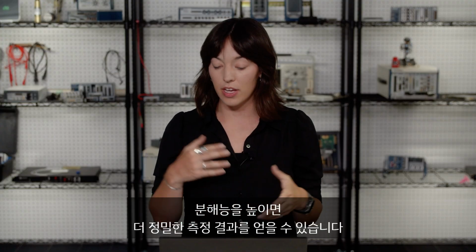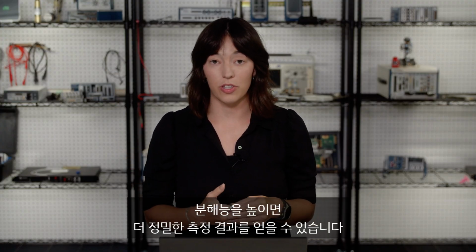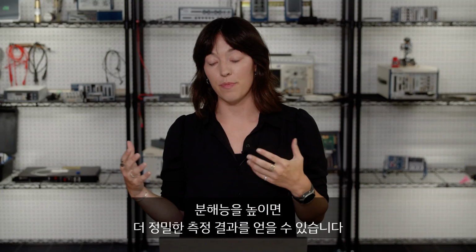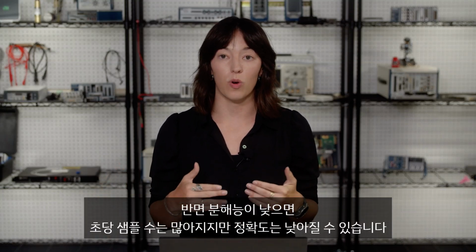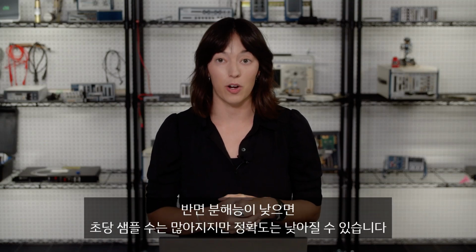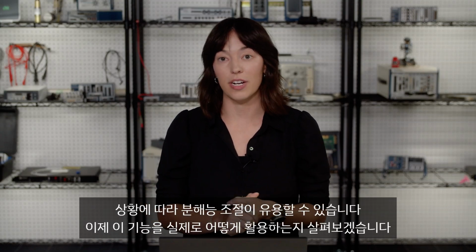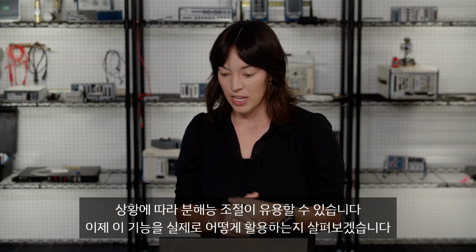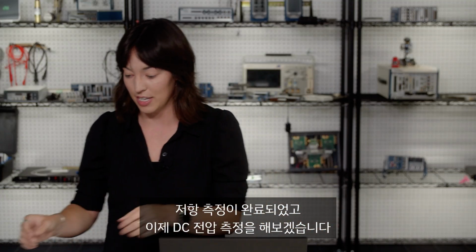One of the things that you might use that for is more digits of resolution is going to give you a more accurate measurement. Whereas if you use less digits of resolution, that'll give you more samples per second, but your accuracy might not be as good. So there are different cases when that might come in handy. We're going to take a look at that as well. We've got our resistance measurement. Let's take a look at some DC measurements.